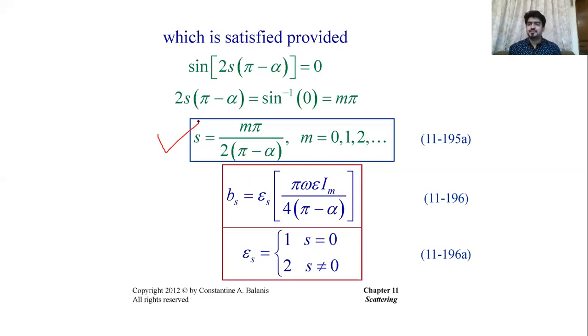Further, if you remember what we did for the electric line source, we can find the surface current density on the source itself using this electric field, and from that we can find that MS, okay, and again using that Fourier series, we can also find the magnetic current density, and from that we will be able to find the expression of the BS when we equate those two.